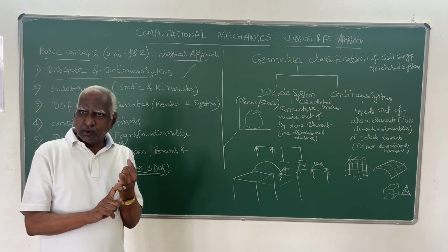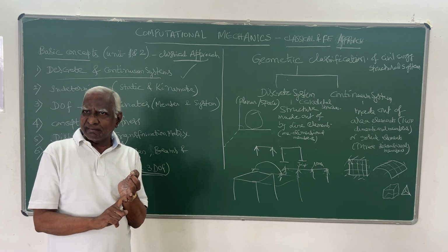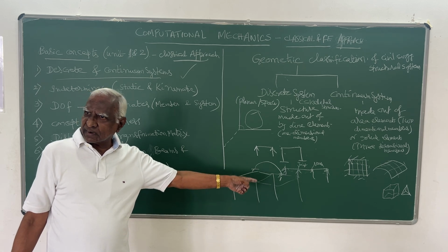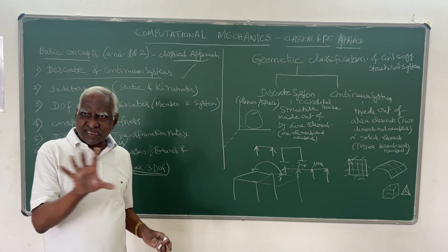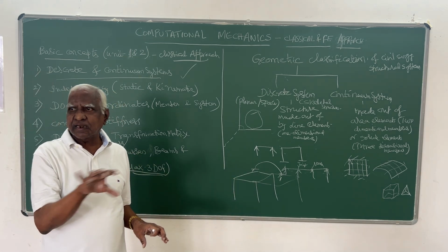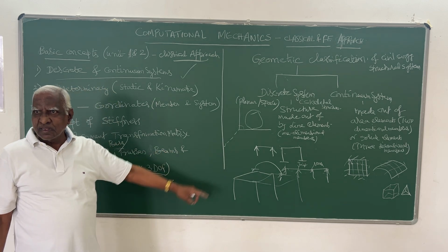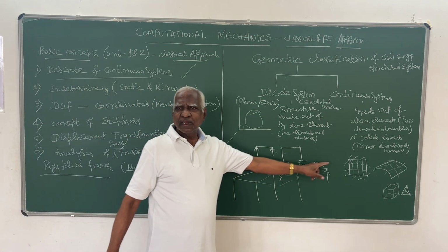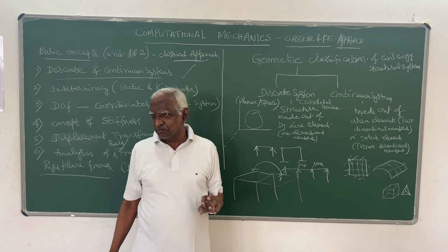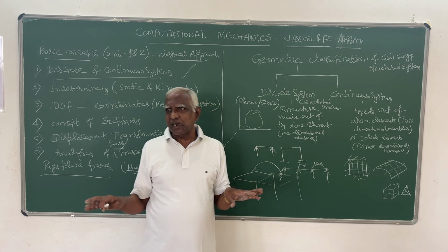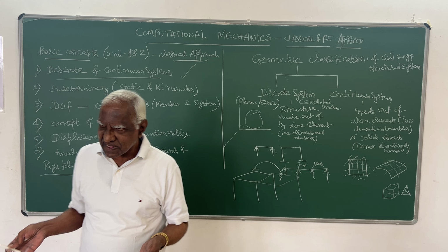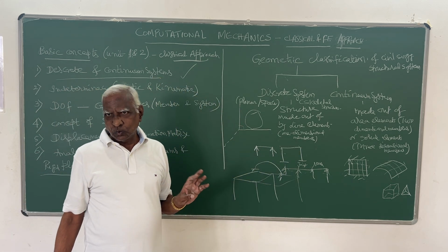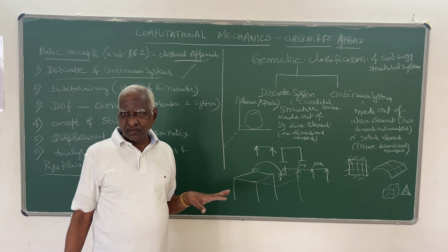Both external loads as well as the internal stresses developed are all considered at the joints. Likewise, when we consider the forces and loads to act at nodes, displacements are also considered only at the nodal points. All the unknown displacements which we have to determine during analysis are also considered only at the nodes or joints. Right?